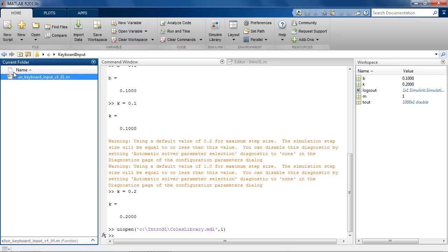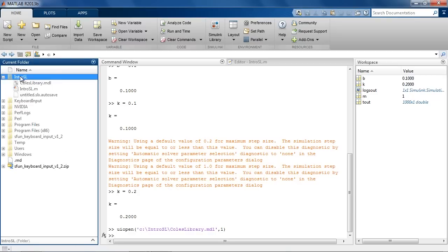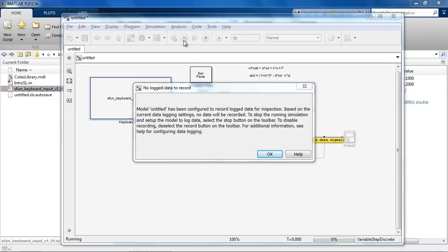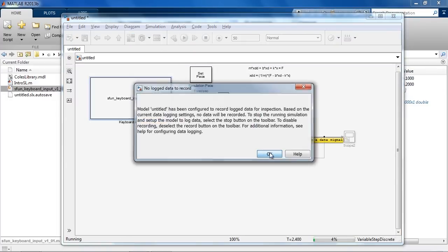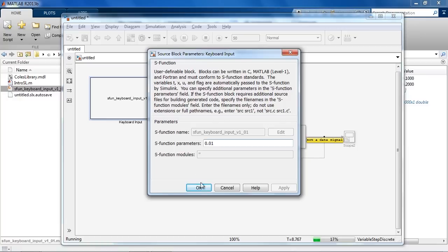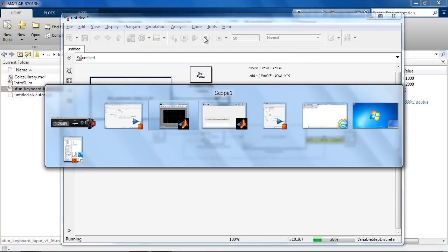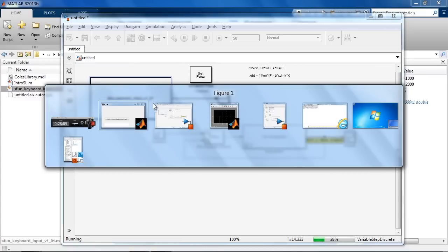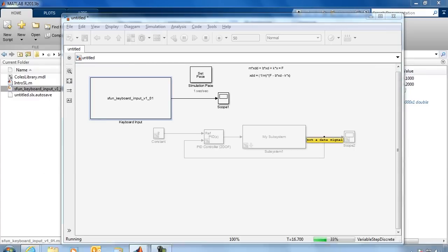This actually brings up the point that if you've got existing code that you want to bring into a Simulink model, this is the way you would do it. You would put it inside of a Simulink function and use that code, and then a block represents that code in your model. So that's really what's going on here. Let me open this up. Let's see. Oh, it must be off screen.